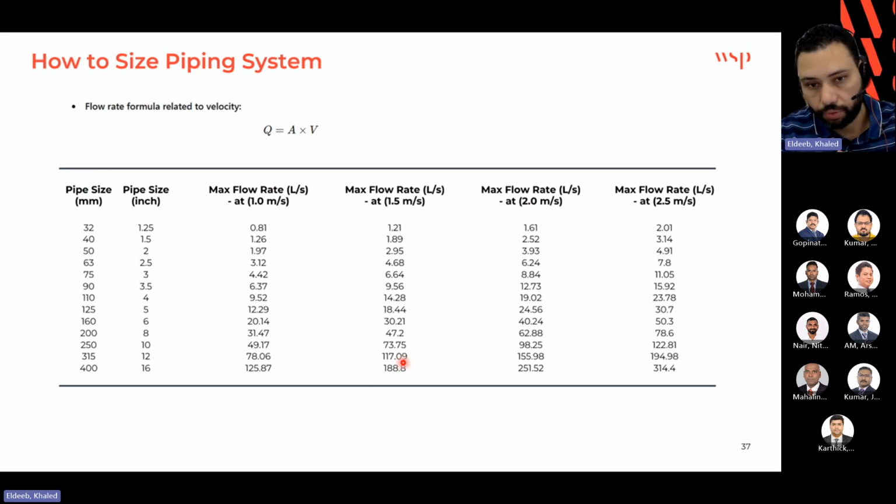This needs to be done if we want to make an accurate hydraulic calculation. That needs to be done usually by the contractor as part of his verification calculation process. But ultimately, believe me, the difference is very minimal. It is not that big to waste your time. So in design, you can do it based on this rough estimation, and then the contractor can make the hydraulic calculation as part of his shop drawing and the calculation verification.